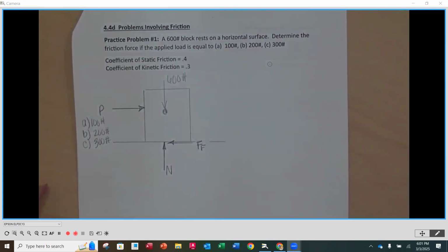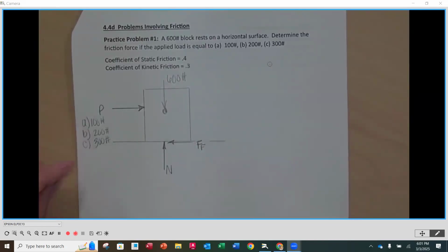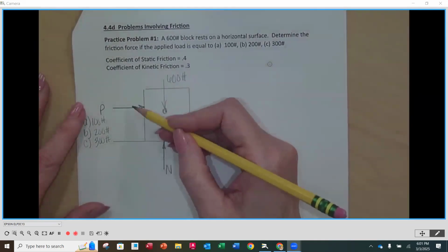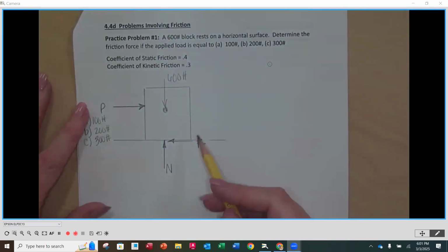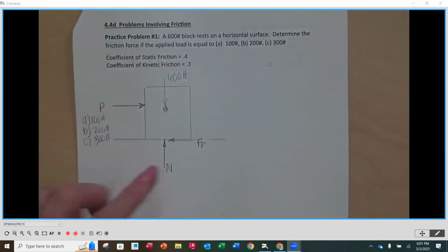When I do a free body diagram, I just do a cross and have the friction force opposing the P. That's okay, but in some problems when we need to determine a height of something, for instance, in one of your application problems, you're going to have to calculate a height. Then you're going to have to have it where it's actually acting because it's going to be an offset distance. Yeah, so I think it's good to represent it similar to what we see here.